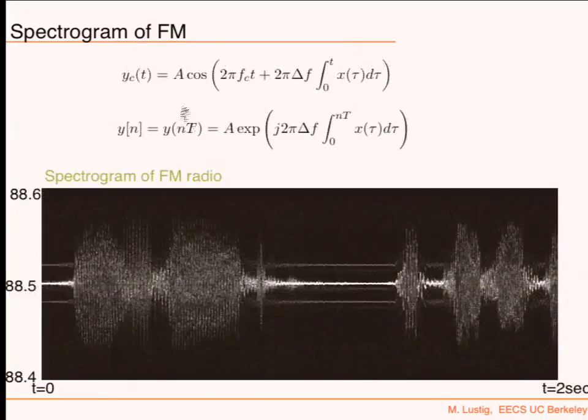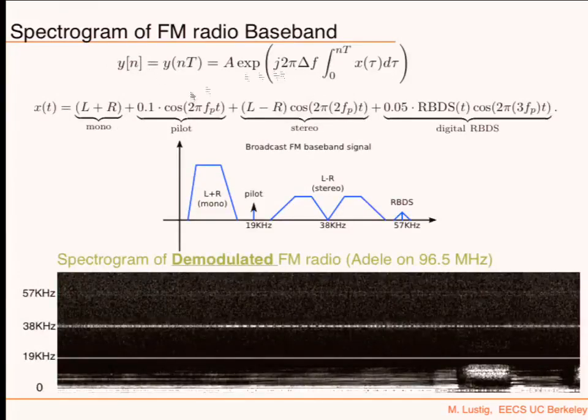By the way, another way to think about this is looking, instead of cosine, at just the analytic signal, which is basically e to the power of that, so the complex value. That will then be a one-sided spectrum. It turns out the SDR will give you this, and I'll explain why it actually gives you this. This is what we receive from the software-defined radio. Now the question is really, what is x of t?